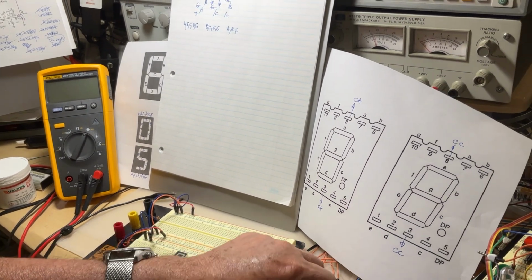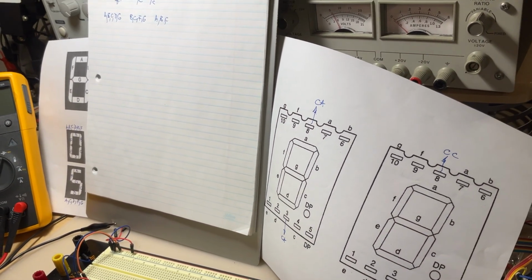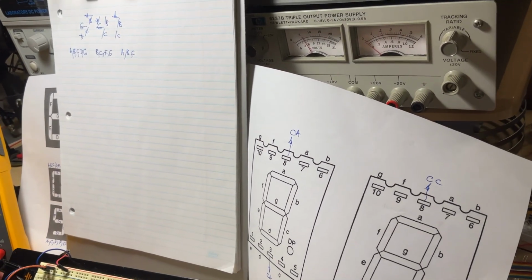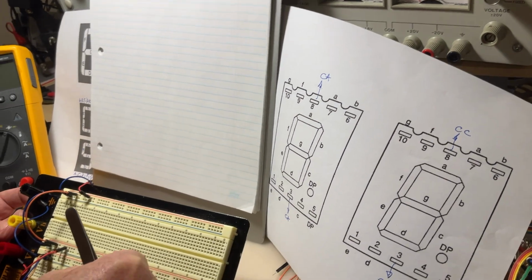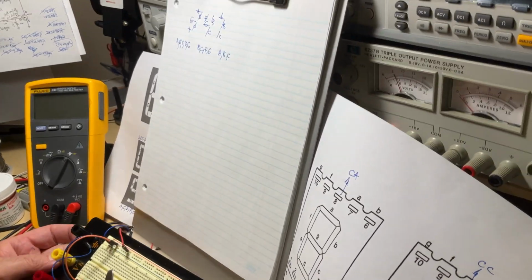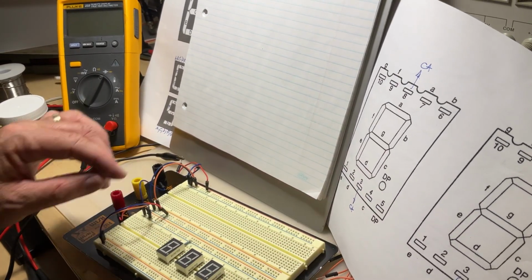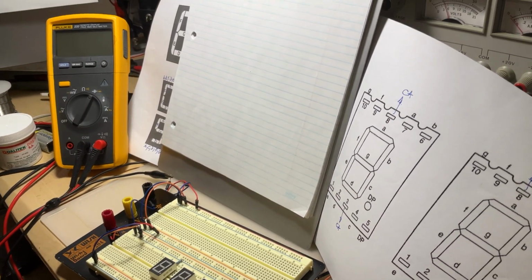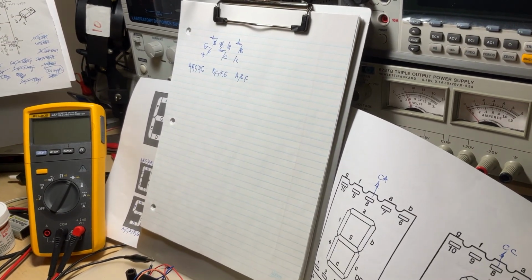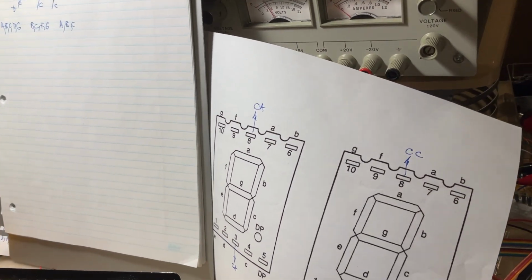I have to connect A. So I pick up a resistor, and A is the pin 7. So from the pin 7, I connect it to any blue line, because the blue line represents the ground. Okay. Then I'm going to connect B. B is adjacent to it, pin 6.